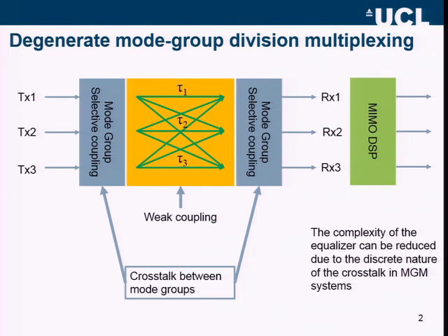However, the crosstalk in the mode mux and demux only generates discrete impulses in the channel response, which will allow us to use a delayed equalizer that can reduce the complexity and also improve the system performance, as all these inactive taps can be removed.